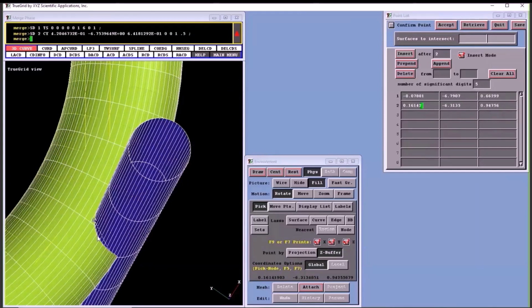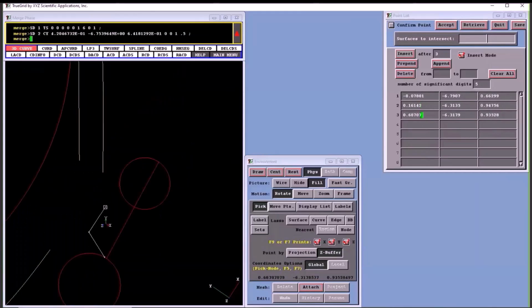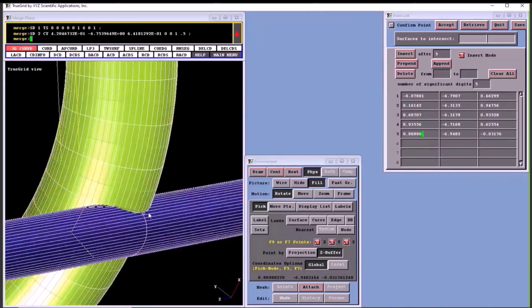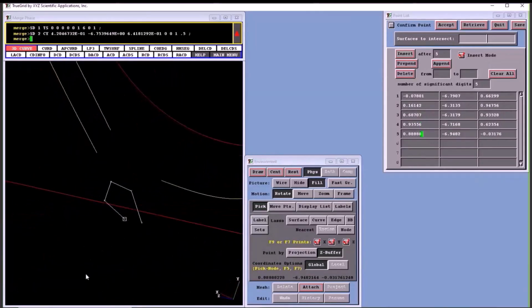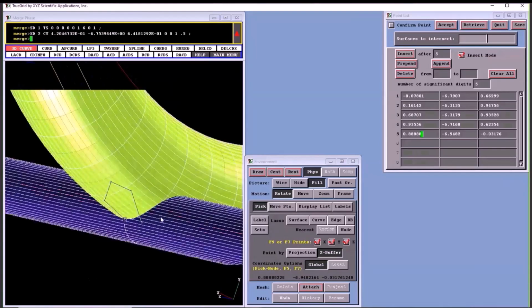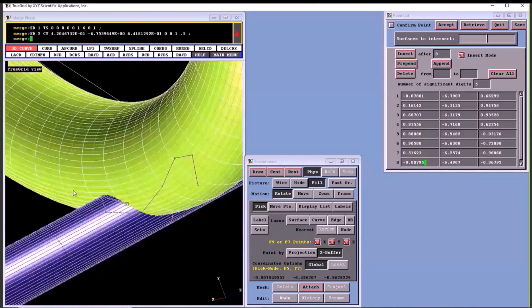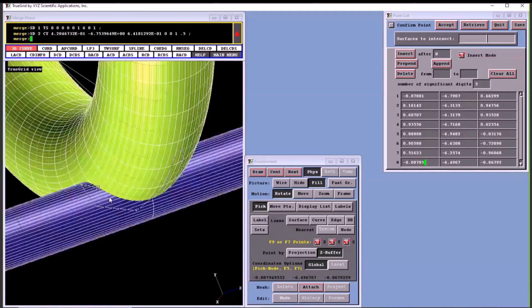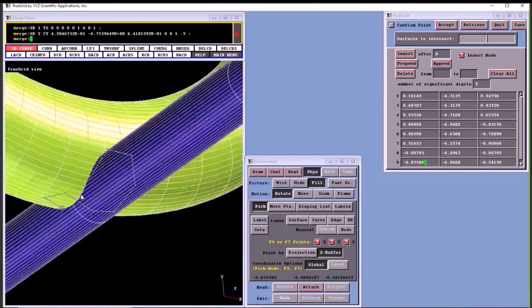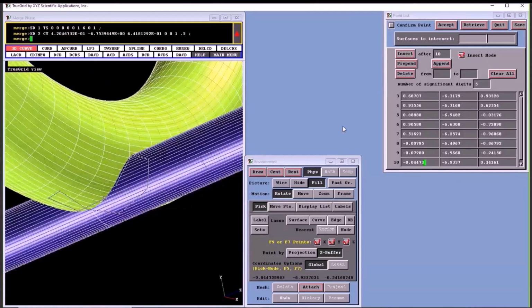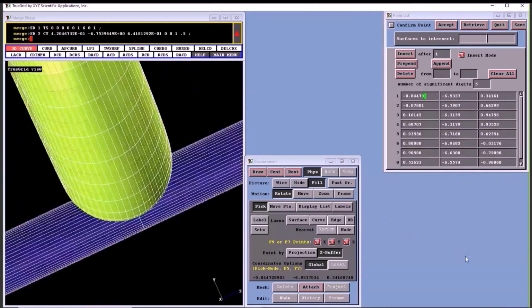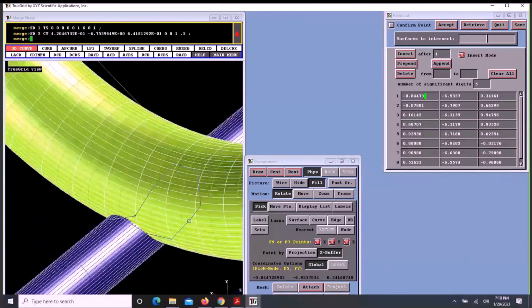Select 2 points on this side and then rotate it a little to get to the other side. Select several points here as well. Also, I'm using the Shift key as I rotate so that I can rotate with more accuracy. This doesn't need to be perfect, and it shouldn't take you a lot of time. After you have all of your points selected, click Prepend, followed by Accept. Based upon this initial shape, the TWSURF algorithm will refine it to result in a smooth curve.